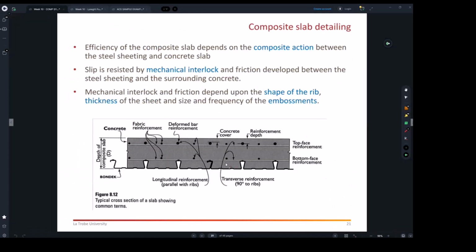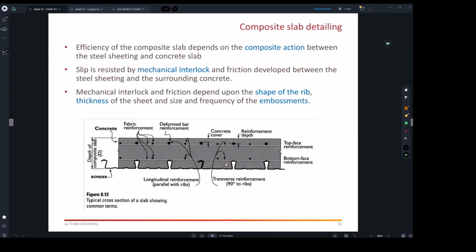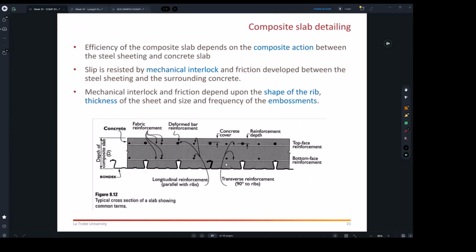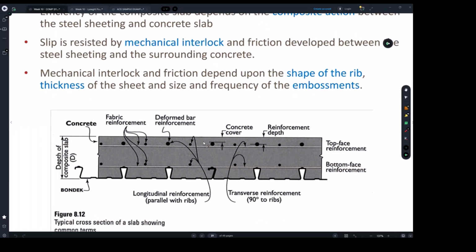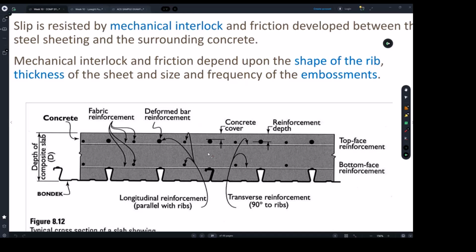Right, so all we talked about so far is the bonding, sitting on and carrying the concrete slab, and having whatever capacity. What I'm trying to say is that the tables that I shared with you do not only talk about the type of decking we need to use in terms of thickness, there are also tables that will help you decide on the quantity of steel we have to use in our slab as permanent placement of steel.